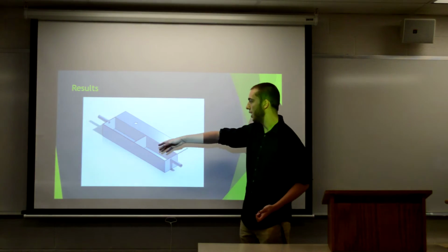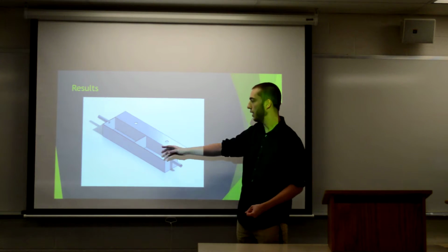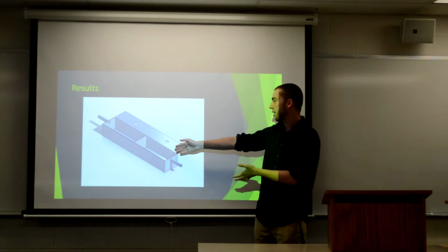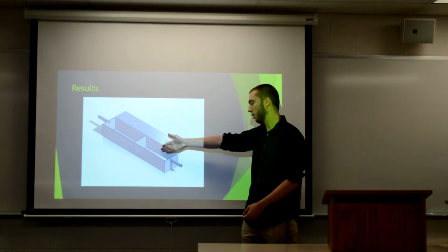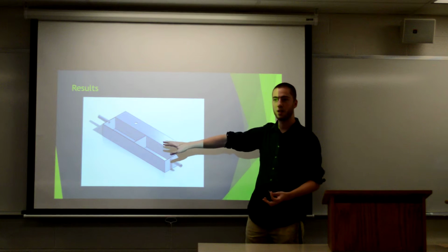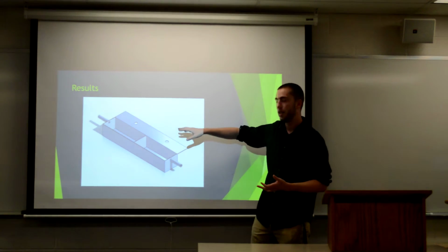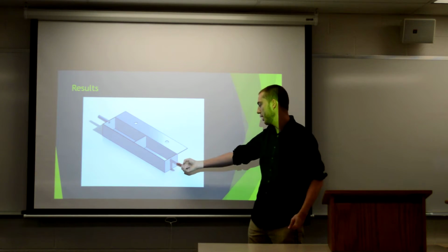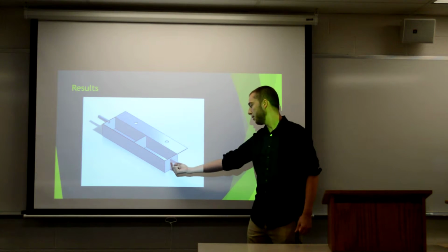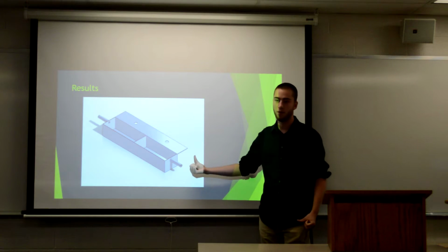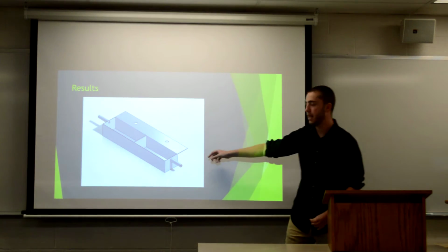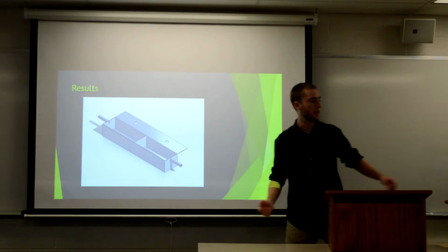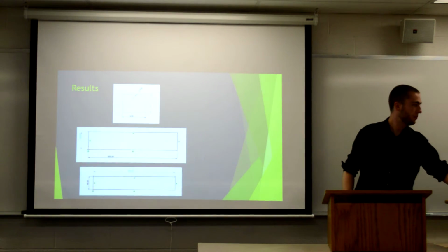It can be closed by a lid. These are the two inlet holes where the waste would be deposited into the two separate containers. The volumes of these containers and the dimensions of the actual digester are listed later in this presentation. And this outlet is for the biogas, so that a pump can pump it out and then a compressor can compress it so that the gas can be stored and used.